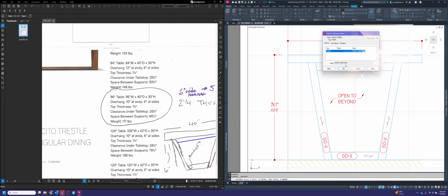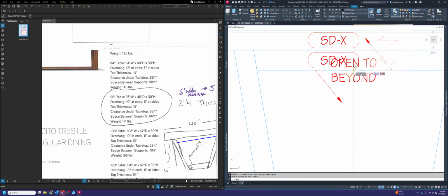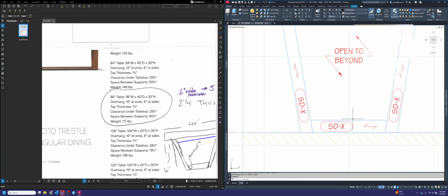What that allows people to see in the drawing, even though you can see it in the axial view above, is that this in fact is open and there is no leg or panel that sits in here. So let's start by centering it there. And then I'm going to center it vertically between there and there, like this.